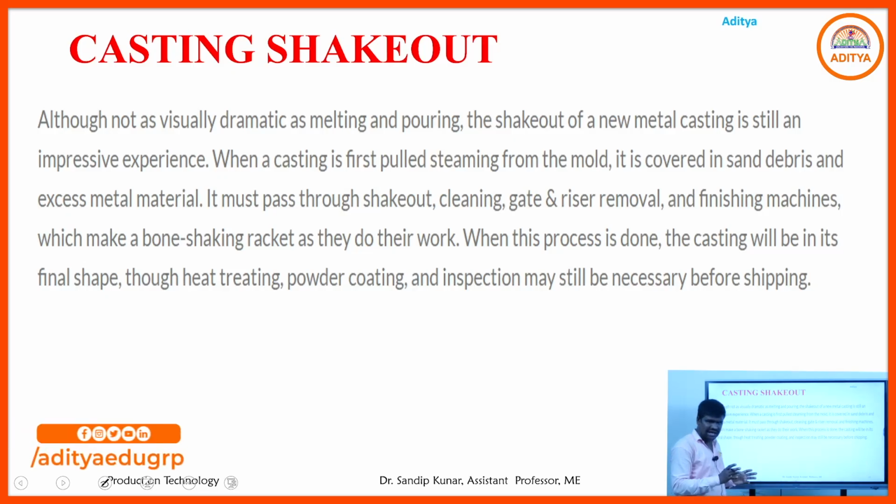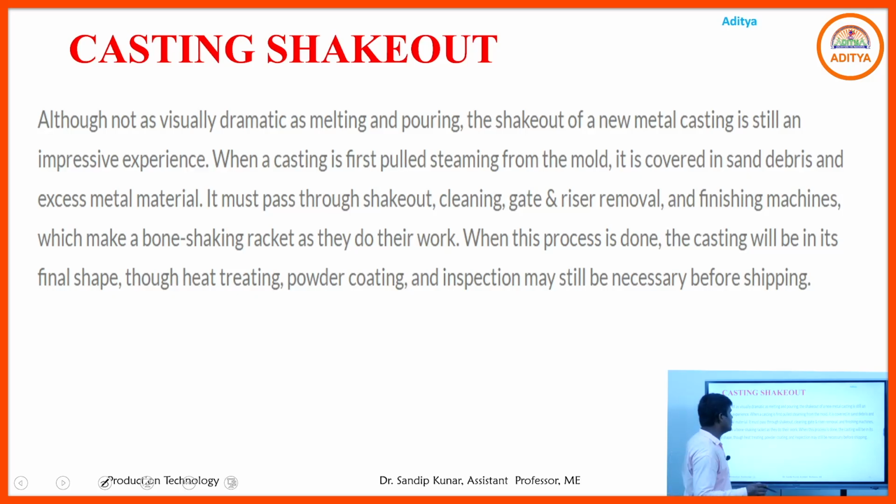After removal of the box parts, the cope and drag, we remove the extra parts, the sprue, runner and riser. After removal of those parts, extra space is created, and we can easily remove the final product without the other parts being affected. That is called casting shake out.